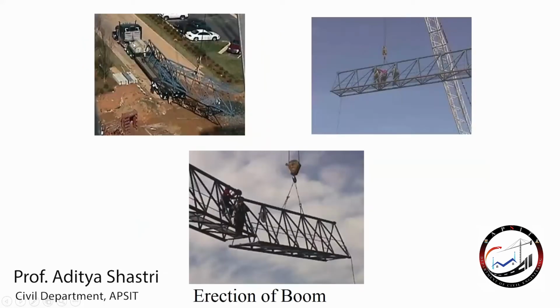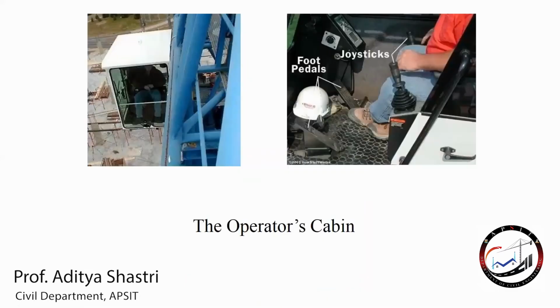So this is how, with the help of these wagons on site, you can supply each and every part separately. And again, the boom, as I told you, for the fixed towers, is also not a single part. Again, it is coming in parts. Those have to be installed on site itself, depending upon how big the site is. Okay, what are the dimensions of the site, where exactly the tower crane is placed, how much the boom has to be extended, how much length is desired. Depending upon that, the elements are fixed to each other and the length of the boom is decided.